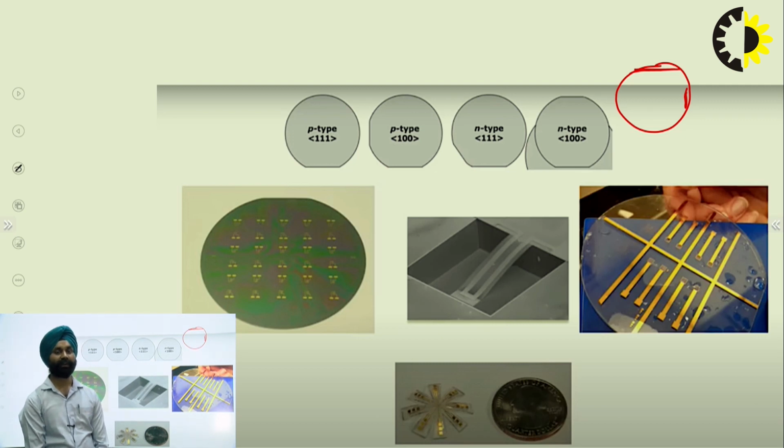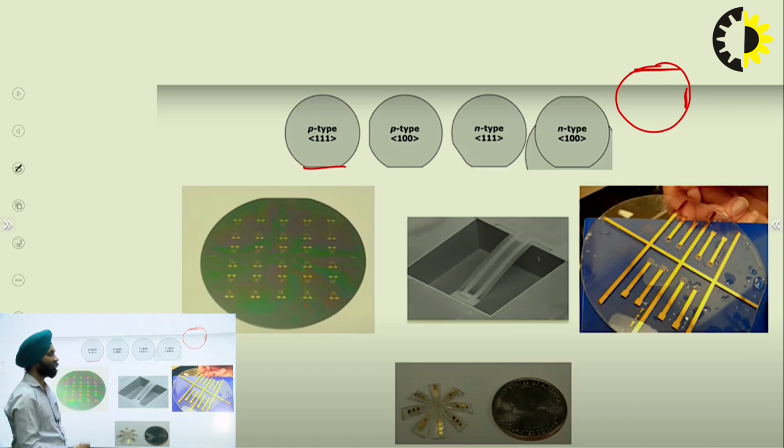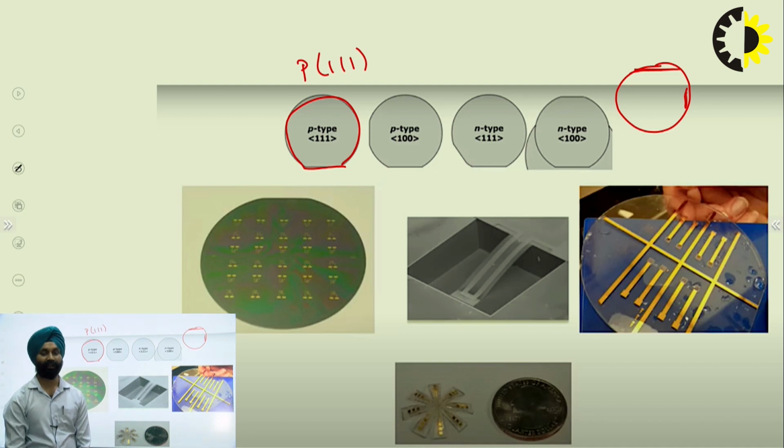If the wafer has only one cut at the perimeter of this circle, this is a p type 111 Miller indices wafer. So now we can see that there are more holes in this wafer and the orientation is 111, Miller index is 111. So all those processes which can increase the chances of volume defects, that is edge dislocation or skewing effect, those can be taken care of.